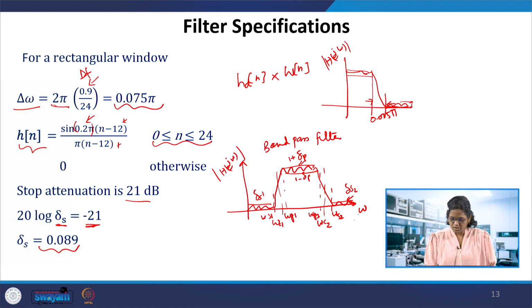The band pass filter can similarly be designed by considering the stop band attenuation of the filter, which decides whether to use the rectangular, Hann, Hamming or Blackman window, the famous four of them. Also, if you choose the Kaiser window, that would be different. The tunable parameters we can get using that.